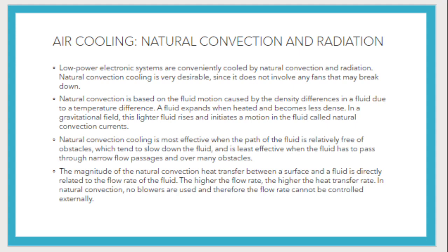Natural convection is based on the fluid motion caused by the density differences in a fluid due to a temperature difference. A fluid expands when heated and becomes less dense. In a gravitational field, this lighter fluid rises and initiates a motion in the fluid called natural convection currents.